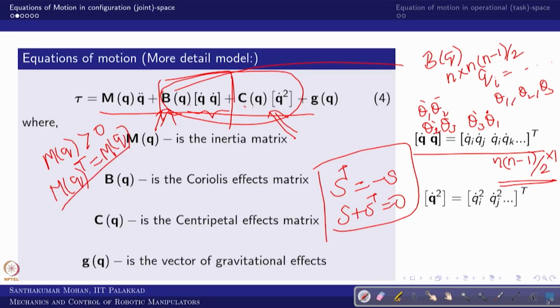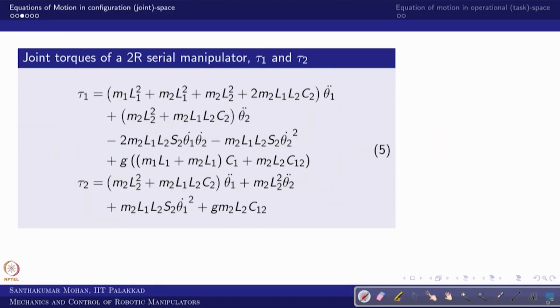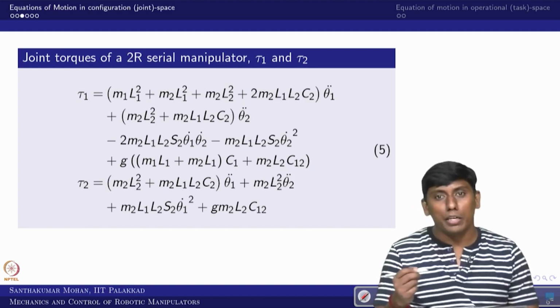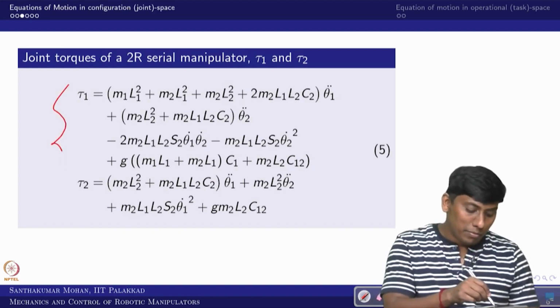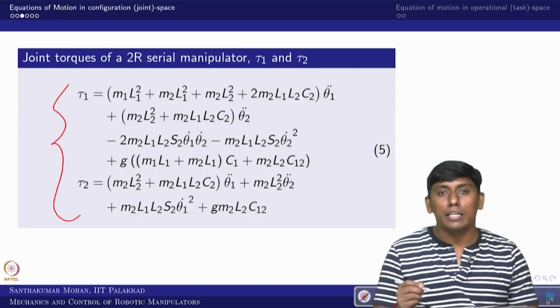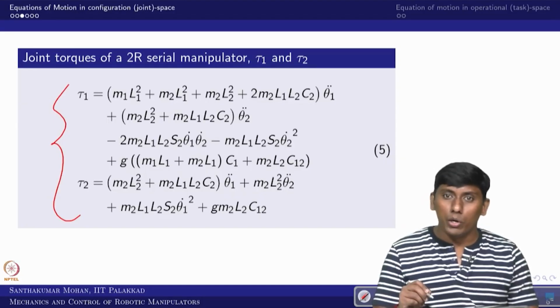So now this is the detailed model, where the gravity term is separated and the inertial term is separated. Further, V of Q comma Q dot has been divided into 2 sub terms. If you want, we can bring in friction as well. But right now we will rewrite the equations which we derived in both the Newton-Euler and Lagrangian-Euler methods.